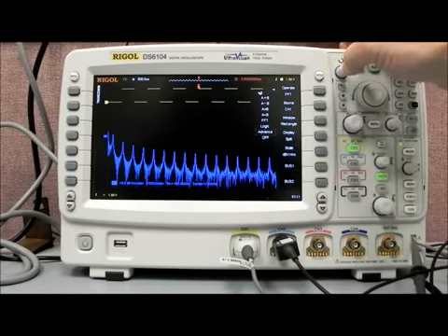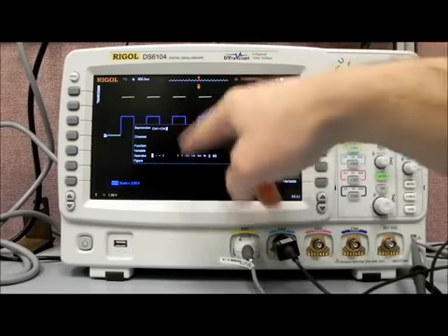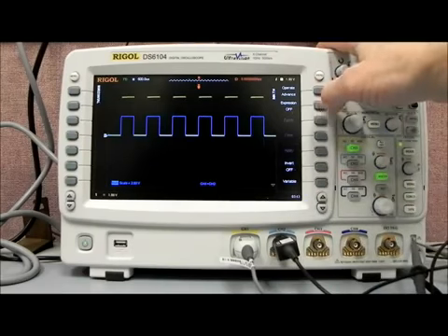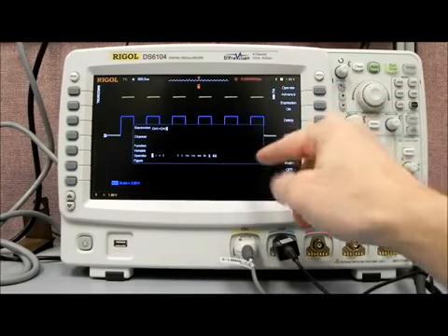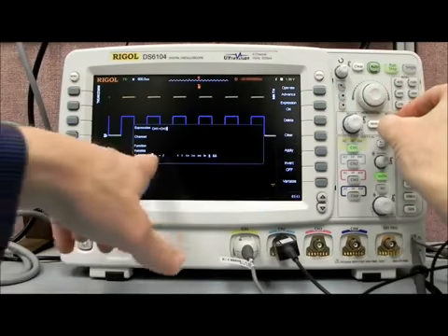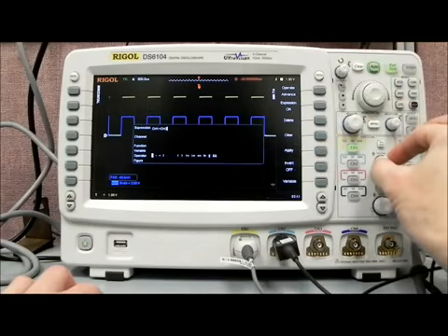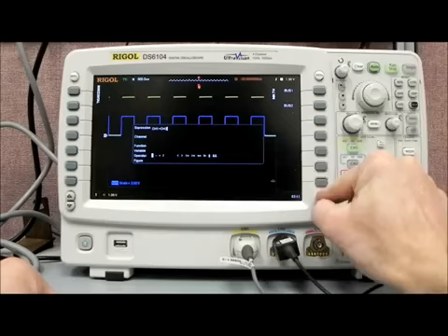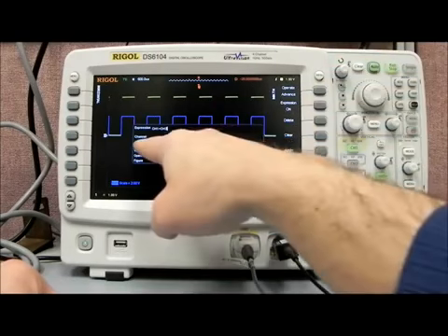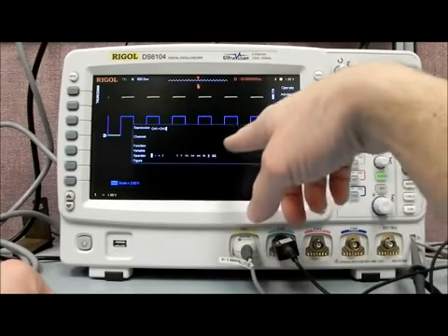Let's go to advanced, because I think that's where some of the processing power really shows here with the DS6000. If we pull up advanced, what we get is we have an expression that we can create. And it's not just A plus B and A minus B. You can actually see we can select channels, and then we can also select the actual operators that we're going to be using. And so if we want to select particular areas that we can work on, we can do integrals, we can do differentials, logs, exponentials, square root, sine, cosine, tangent.